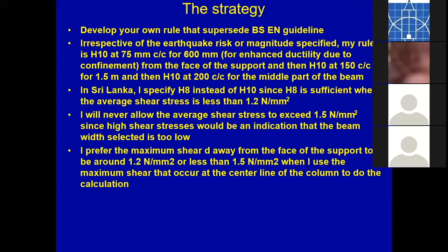And then you might adopt a different philosophy. Now, what is that philosophy? You might think, okay, because we are using Eurocode, we can use high strength materials. If we can tighten the site supervision to the level that we use 50 megapascal concrete instead of 30 megapascal concrete, we can make many sections smaller. And that way we can save money.